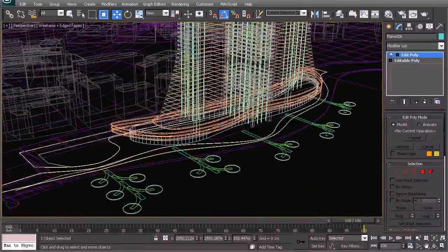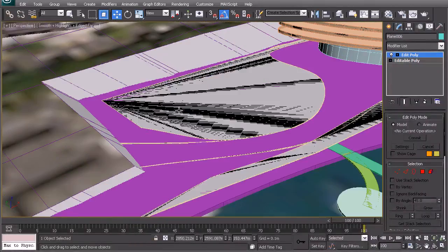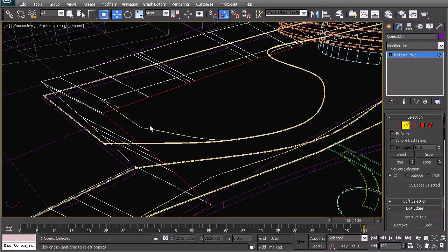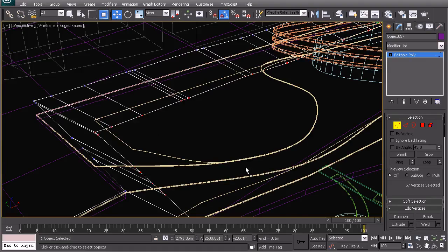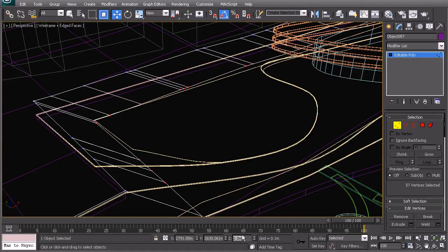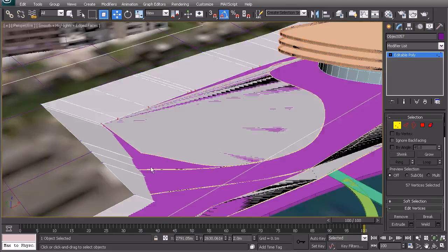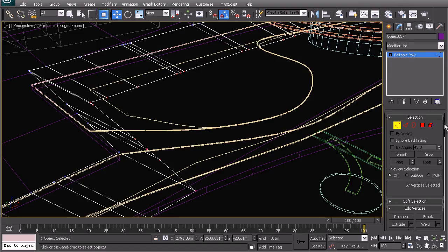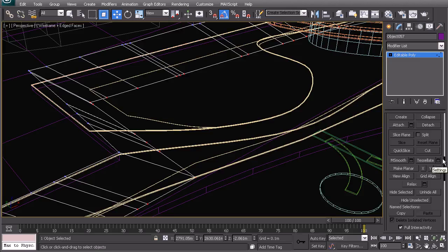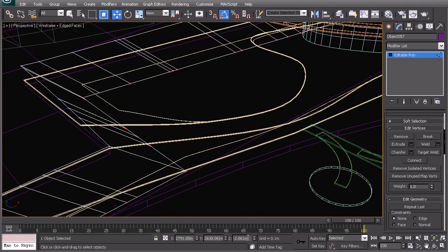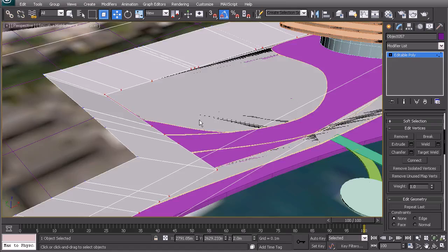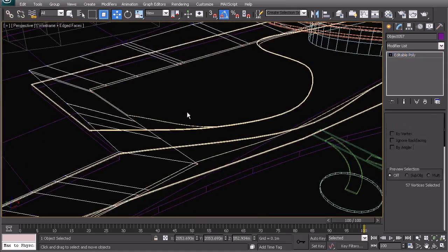And let's just have a look at which areas we will be adding grass to. Now we want to add grass here to this area. We want to add grass there. Now we need to move up this bottom line of that berm to 2 meters, which is the height of our platform podium. First, before we do that, let's just move them all planar in Z. And then let's move this number to 2 meters. Just get that right. So if we have a look now, they're all sitting at the right plane.